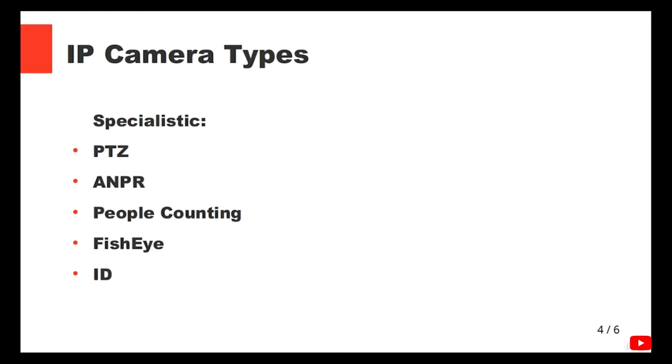So when somebody enters, it's automatically displayed on the monitor so they can see themselves. It's a deterrent. Typically the camera will have analog and HD output, and analog is used for the monitor and HD is used for the DVR.